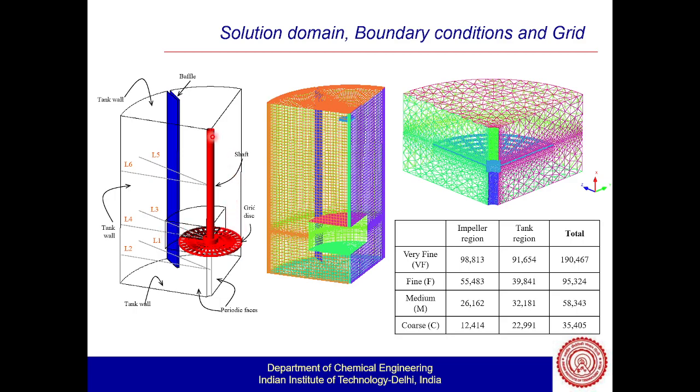Yes, 3D space. So what we do is we have this 3D space. We divide the domain into small cells, as you can see here. You can see on the screen that I've divided this domain into small rectangular cells. In these small rectangular cells I'm going to solve the momentum equation and the continuity equation, if it's a non-reactive, non-heat transfer flow. But if heat transfer comes into account, you have to solve the momentum equation and the continuity equation, and alongside that, you have to solve the heat transfer equation. So that's what I'm saying.